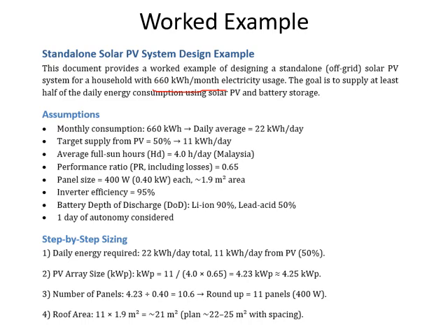Sometimes we run the oven, and those days, when we are running the electric oven, the electricity consumption is higher. Vacuum, so these are the strong power equipment. The vacuum cleaner we use is like 1500 watts. So even if I run it for half an hour, I'm consuming at least 0.75 kilowatt hour, right? So this is a standard household in Malaysia, so it's 660 kilowatt hour per month.